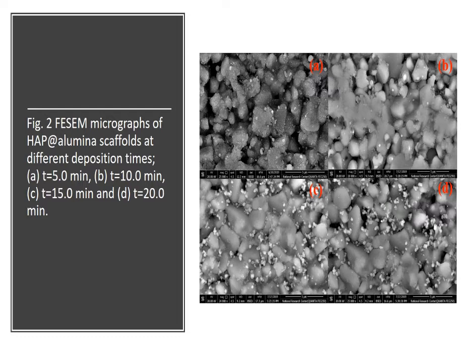The composition with high deposition time, at time equals 20 minutes, looks to be well covered with a high content of small spheres belonging to the hydroxyapatite. These spheres reduce both surface roughness and porosity ratio.